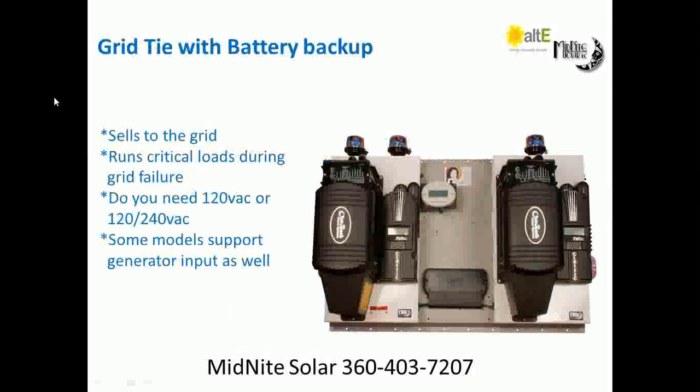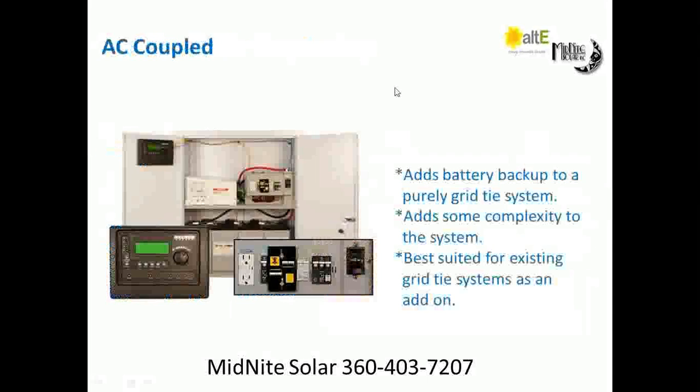A lot of people have bought purely grid tie systems and were not aware that it wouldn't have power when the grid was down. And now, unfortunately, they're candidates for AC coupled systems. And I say unfortunately because that means they've got to spend more money. So AC coupled, again, adds battery backup to a purely grid tie system.